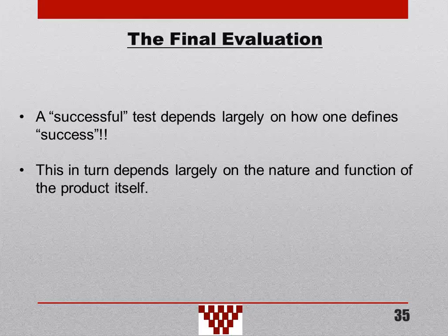results. Now, the severity of that input, as Edmund pointed out, is likely to be higher than the mean level of the distribution environment. In fact, we want it to be higher. We're actually targeting the 3 sigma level. In other words, we want to encompass 99.4% of all of those potential hazards in the distribution environment if we can. And that's the whole purpose of this accelerated or somewhat more exaggerated type of testing that we do.